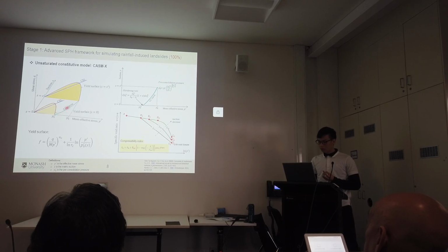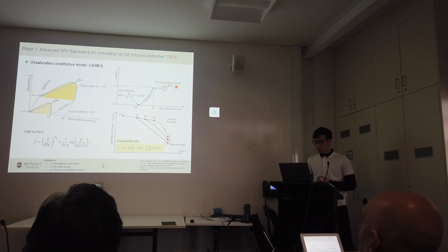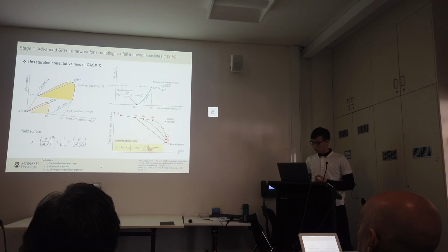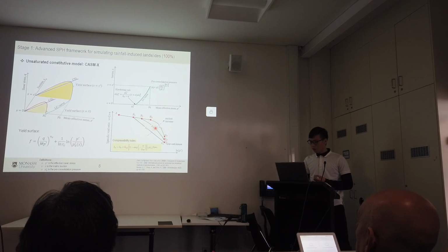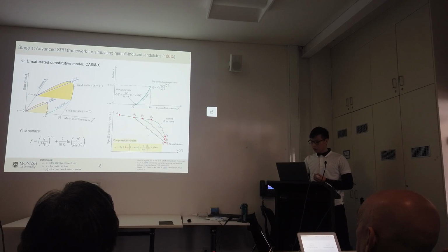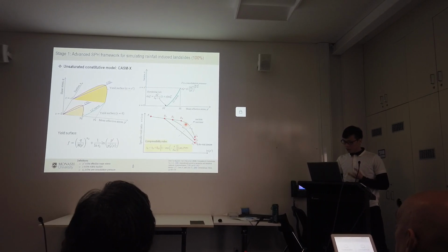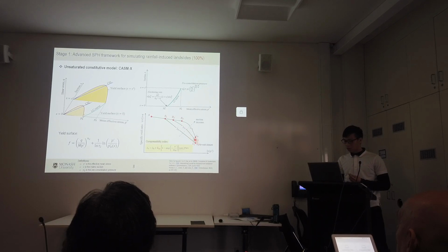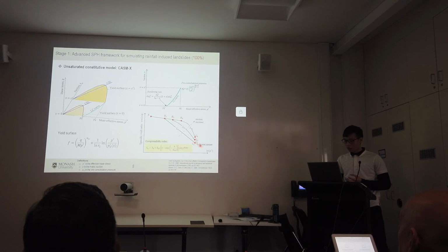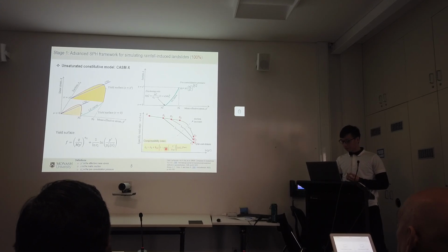For example, the LC curve, you can see here, describes how the preconsolidation pressure changes with suction. Now if you are working in the area of unsaturated soil, there is a lot of literature discussing how the compression curve evolves under different suction. Traditional approaches often assume this is a linear line, but experimental evidence demonstrates that this compression curve is nonlinear, and more importantly, it actually converges toward the saturated compression line as the air-entry value is approached. So to capture this important behavior, we propose a new compression index rule.